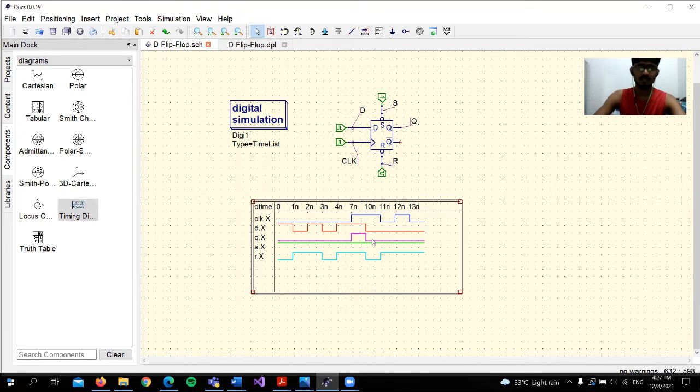After that, the D input became low, and the CLK input is pulsed momentarily from 11 nanoseconds up to 14 nanoseconds, or 13, but the output was cleared to 0 because the step was carried out from 10 to 11. We can see here that from 11 to 13, the CLK was going through a positive going transition, while D is in a low state and Q is also in a low state.